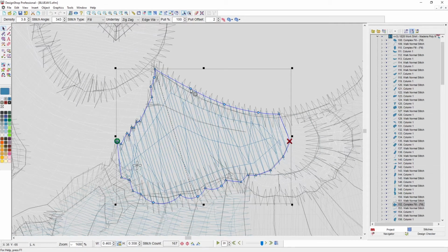If I wanted to edit those wireframe points, I would have to click on them. I can click on them one at a time, and I could move them. If I wanted multiples, I could hold Control and click on them in the view window. And now if I move them, I'm going to get them all. Let me hit undo real quick. Move them back. I could also use that custom point selection tool to draw around the ones that I want. So now I only grabbed those two. I grabbed every other one. I can do that. Let me hit undo.